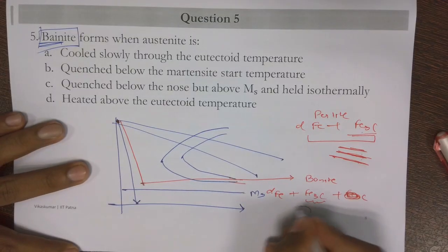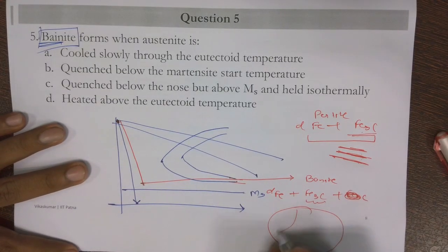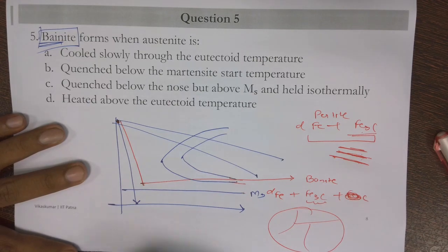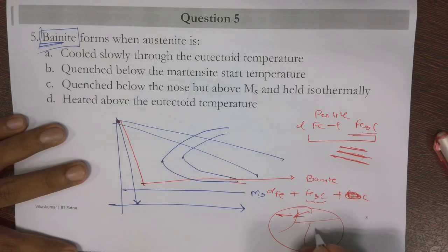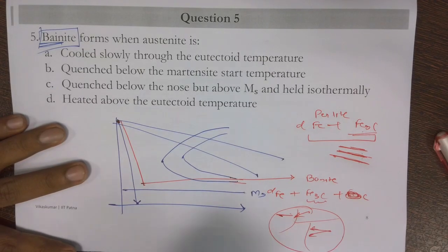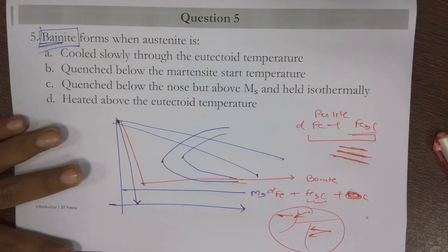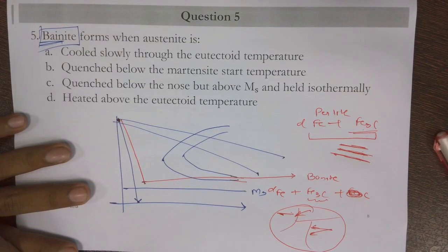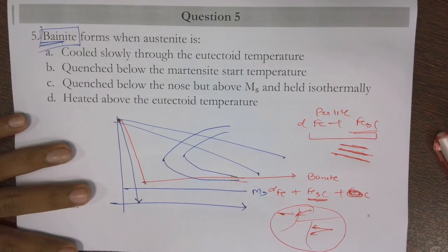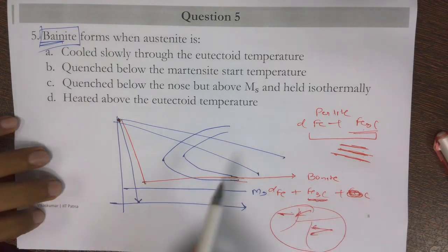This is where the bainite differs. The difference is in the microstructure. And why have we produced bainite? It has more hardness. See what we did: when we cooled it very fast, the temperature is low. When the temperature is low, growth is not there much. But what is there? It's nucleation. So nucleation is happening fast here, but the growth is not happening. So this is how it will go.